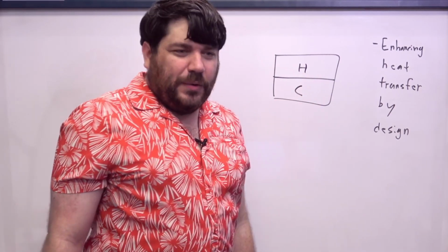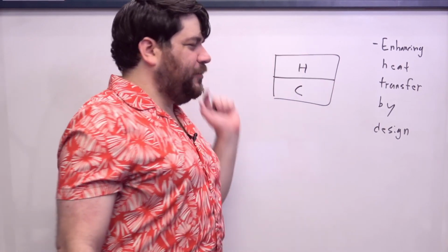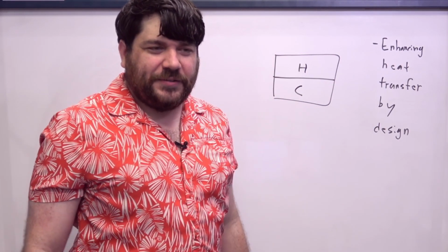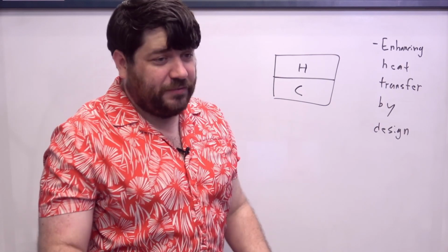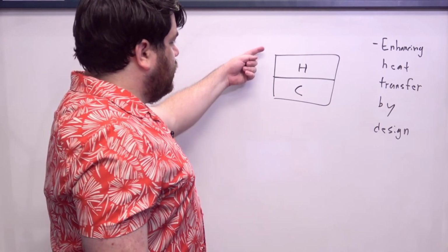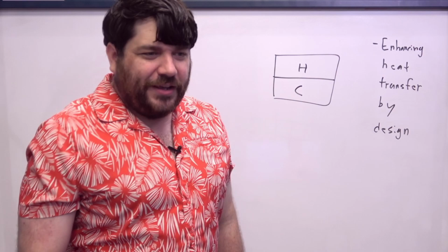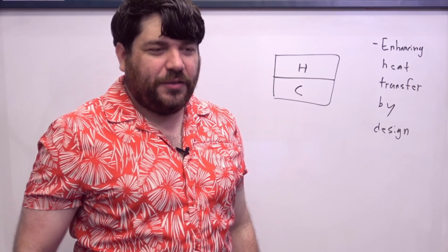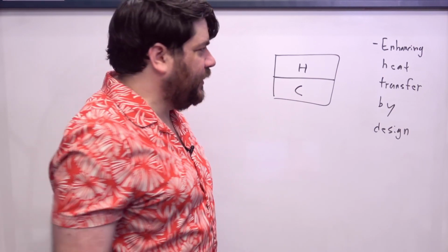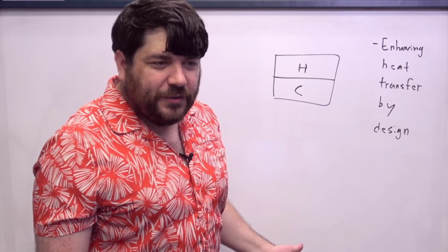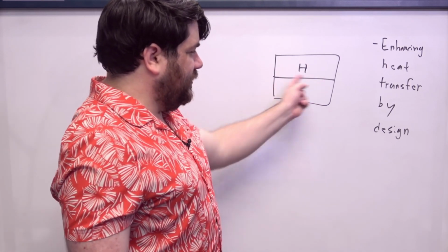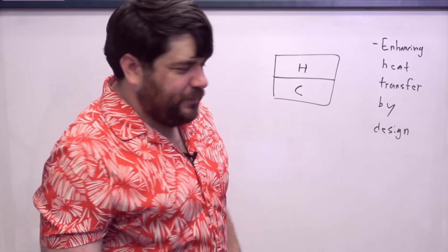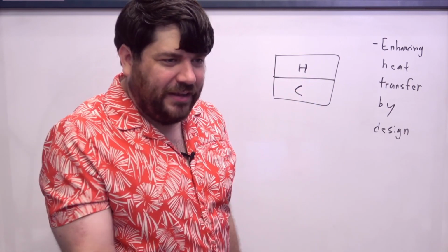And then we can ask ourselves, well, if we assume the standard assumptions for simplified heat transfer, then we can try to see what this would look like if we model it as a thermal circuit, as a thermal network. So what does this look like? Well, we have liquid in contact with a solid object, which is this separating thing.